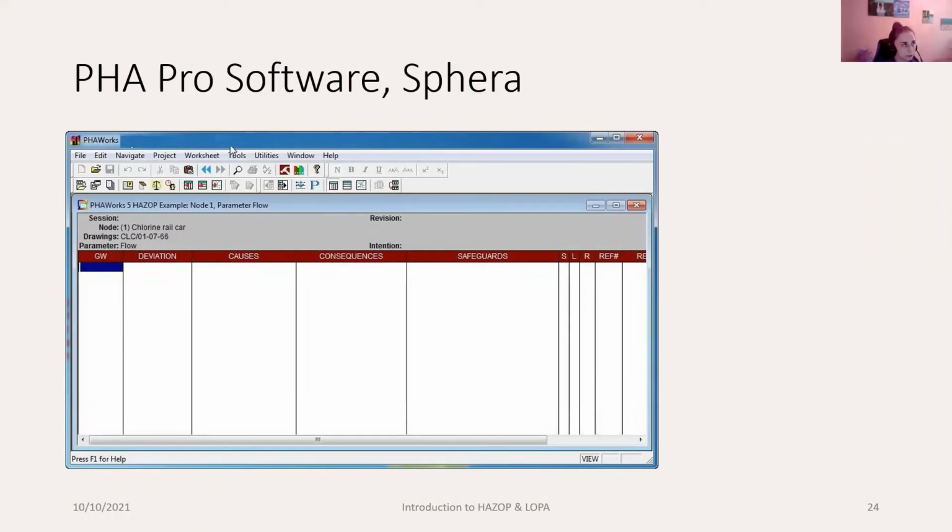This HAZOP sheet is used, first of all, to add additional safeguards. So if you have an emergency situation, for example, that the tank had a low level, we add an additional safeguard there. There shall be operating procedures which state that if this happens, you should act in a particular way. The operations team have their own procedure which they follow in case of emergency.